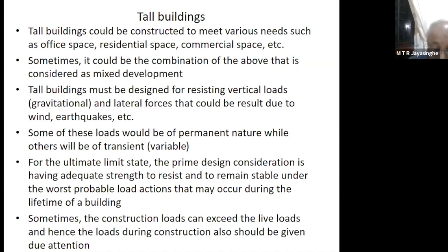And the advantage of minimizing the vertical load is very evident when you have end-bearing piles. But if you have good soil, you have the skin friction in addition to end-bearing, then even if the dead weight of the structure is slightly higher, you are okay.